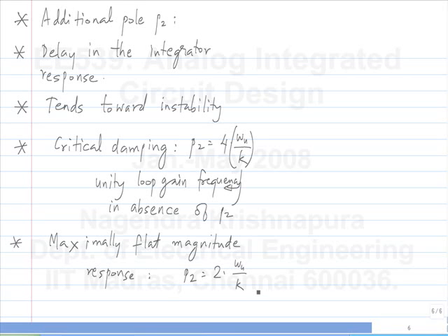Do we specify any certain criteria to what extent we can use the instability criterion? Yes. One criterion is critical damping. Maybe you specify that there should be no overshoot in the step response. When you apply a step, you know that if it is overdamped, it will go slowly, and as you move the poles closer together, it will move faster, but it will still not overshoot. So this is the fastest you can settle without overshooting.